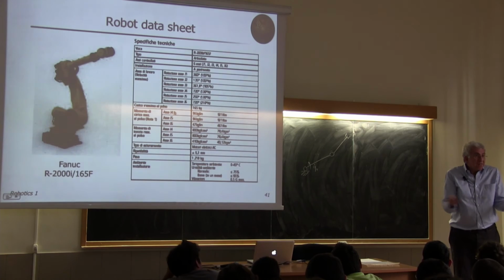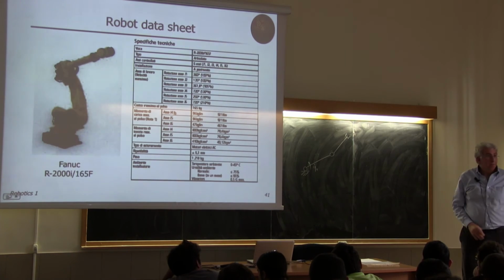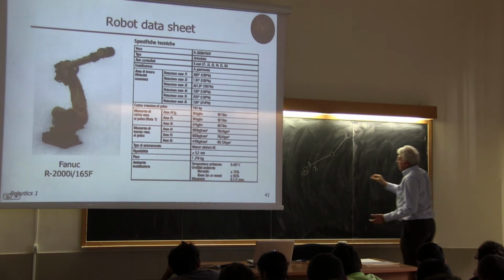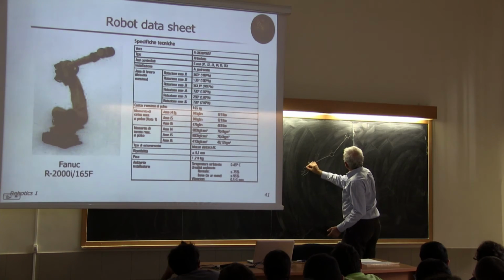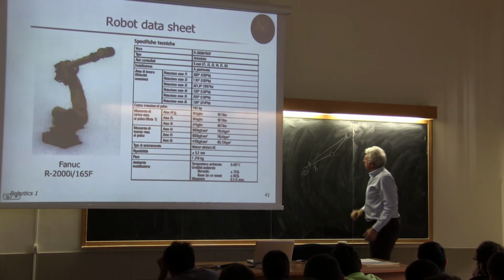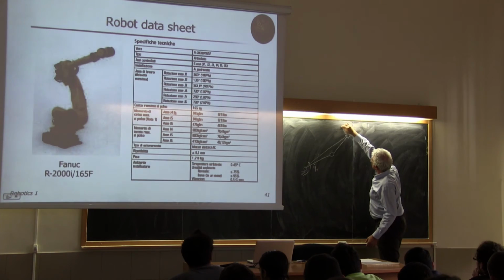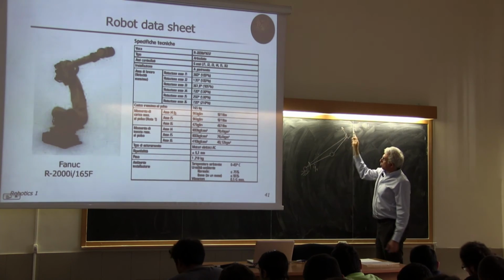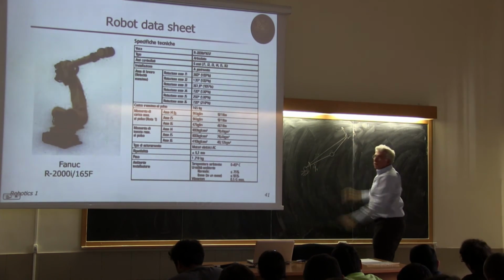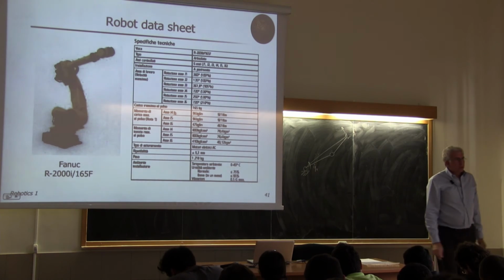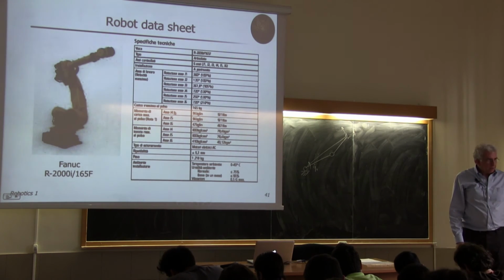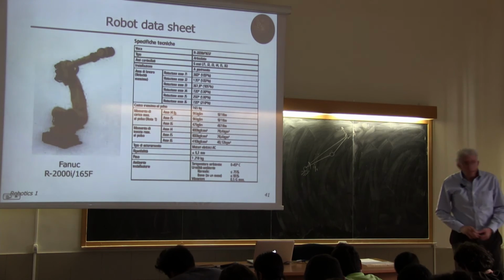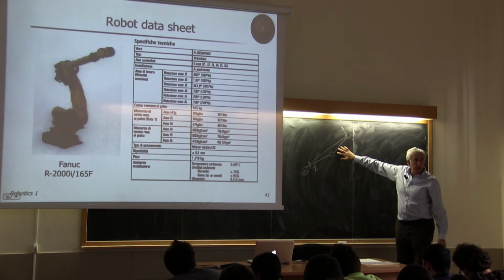Let's say linear velocity. Now this moves in the plane. So more or less, you can do this graphic computation: the velocity will be orthogonal to the line connecting this joint with the end effector. Okay? Do you agree with this? If this joint is not moving.